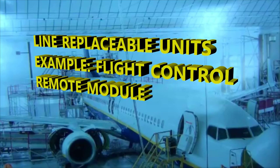All right, the components that you have are line replaceable units, your LRUs. Is your flight control, remember the flight control remote module that I mentioned earlier? Those are for your servo controls. And then you have your EHSV. That's a solenoid valve, your electrohydrostatic solenoid valve. You also have an active damping solenoid valve, a soft/hard damping solenoid valve, and your transducers. All of those components of the servo controls are line replaceable units.